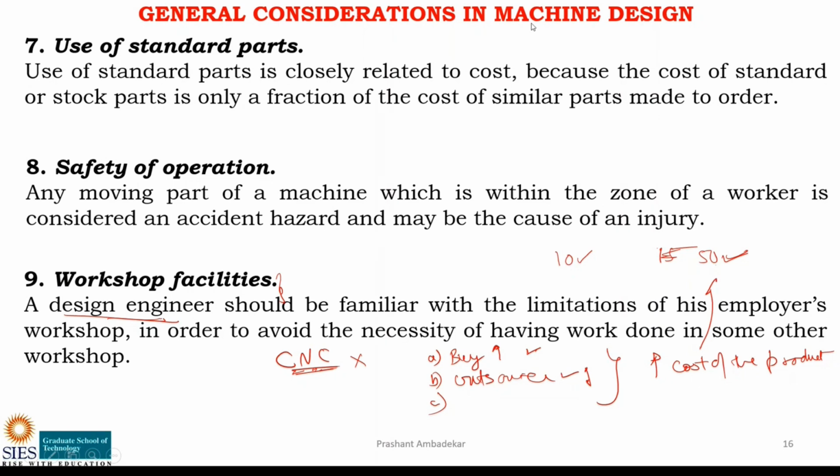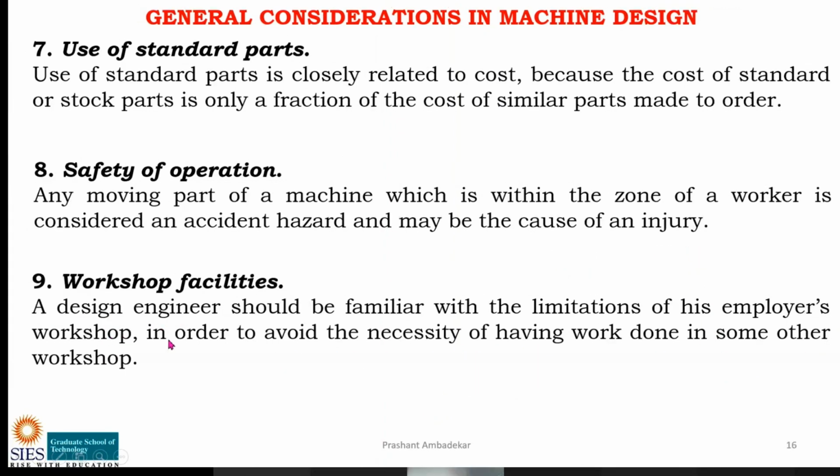So it is again a consideration when a part is to be designed. For example, if it is suggested that a tapping operation is to be done, but there is no provision for performing tapping in the particular workshop where the product is manufactured, then what will happen? The product has to be given to someone else where tapping will be done, and then it will come back to his own workshop. Because of this, number one, the cost of the product will increase. Number two, the time required for manufacturing will also increase.